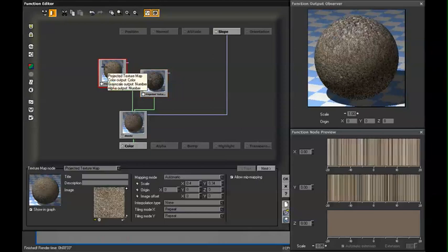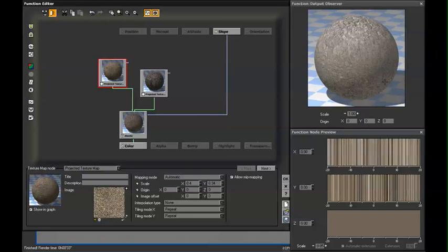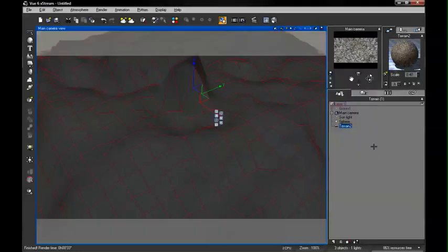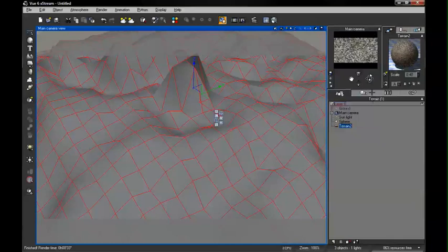But the main problem is this other surface that's appearing with steeper areas, and we don't see it so much showing up on the preview, but on the terrain you can really see it, and whether or not that's just because the resolution of the terrain or the way it was generated, it can be difficult to tell. But let's change this mapping mode to faces. And hopefully we don't get any seams that way, because sometimes with faces, the overall scale of which it projects onto the specific object can be a little bit off, and you might not always notice the way it's going to look.